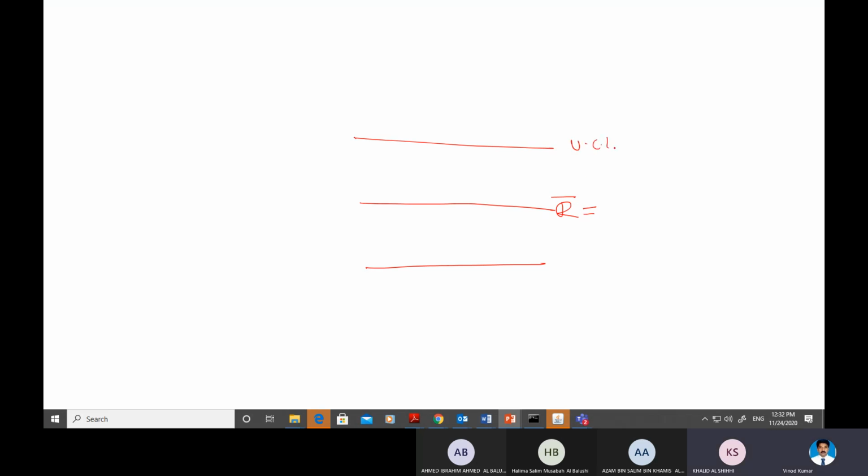Upper control limit, can you give the values? R bar is 6.66. And upper is 15.1848. Lower is 0. If it is minus, you can take it as 0. So here you are going to plot not R bar, but the range values. Here the axis will be the sample number, like before: 1, 2, 3, 4, 5, and finally 6.